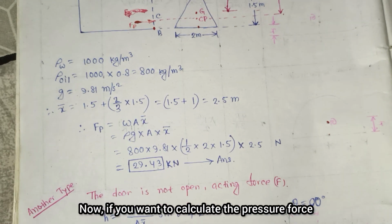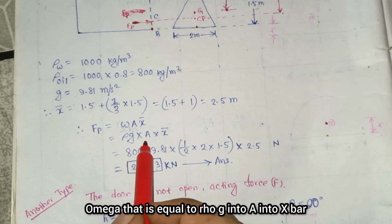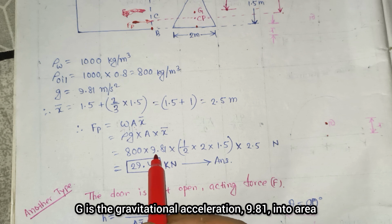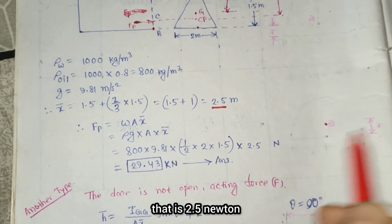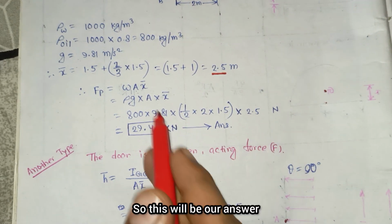Now if you want to calculate the pressure force, we know that the pressure force is omega into A into x bar, that is equal to rho g into A into x bar. Rho is the density of oil, that is 800, g is the gravitational acceleration 9.81, into area, that is half into 2 into height 1.5, into x bar, that is 2.5 Newton. So from here if you calculate this value, that will be equal to 29.43 kilonewton. So this will be our answer.